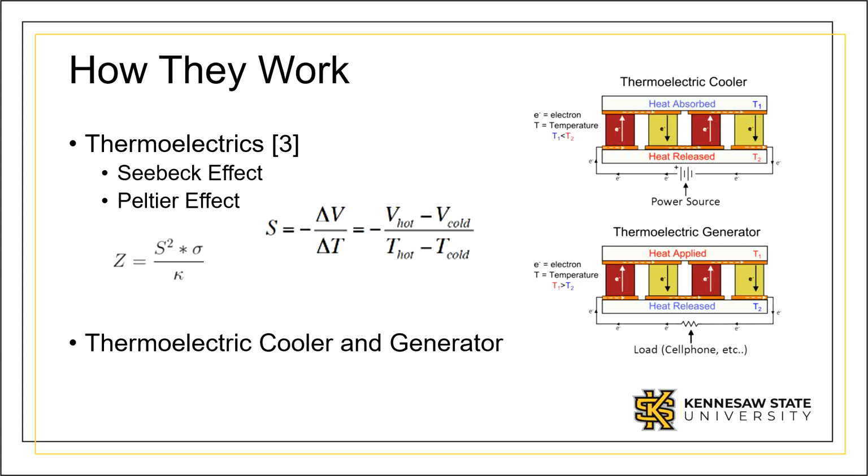A negative Seebeck coefficient results in electrons being the dominant charge carriers, whereas holes are the dominant carrier in materials with a positive Seebeck coefficient. The majority charge carriers are said to move away from the heated side toward the cooler side. Minority charge carriers move in the opposite direction, but at a slower rate.